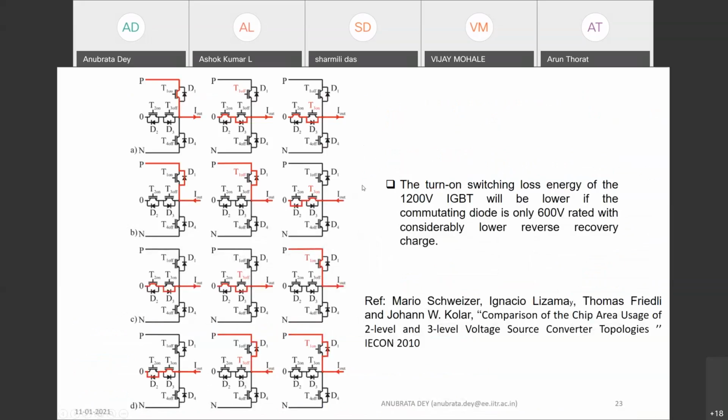And very importantly, this turn on of the switching incurs a lower switching loss because these bidirectional switches clamping the neutral point use a lower voltage rating. That is the main reason it gives lower losses compared to your NPC or ANPC structure, because of the lower reverse recovery charge associated with these anti-parallel diodes, they have low losses during turn off time.